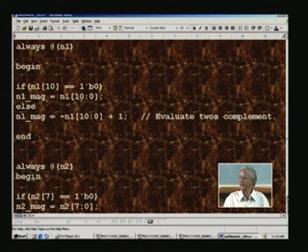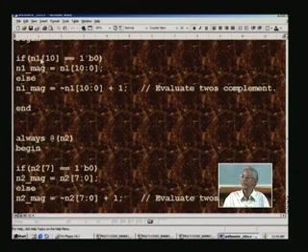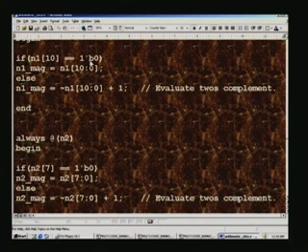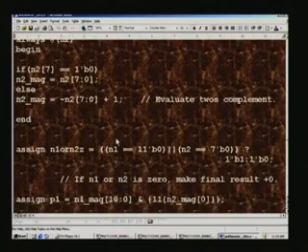Otherwise, that is if the MSB, the sign bit, is 1, the else gets applied, in which case what we do is take the 2's complement. This is nothing but 2's complement. We have already seen we can get the magnitude merely by taking 2's complement, and that is how we are extracting the magnitude of the two numbers and then applying the algorithm hereafter.